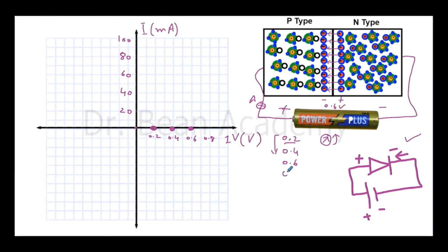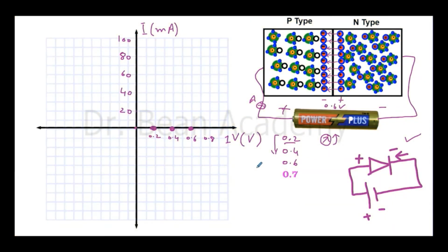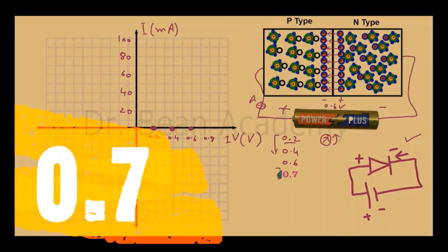So next I change the voltage to, now the applied voltage is, now tell me what will happen. Here the magic will start. These electrons will have enough push or enough energy to cross this potential barrier in the middle, which has been set up as a reverse voltage of 0.6, and now the applied voltage is 0.8.